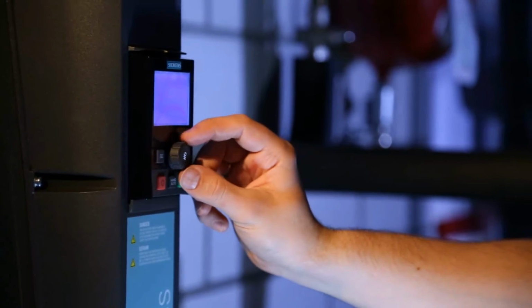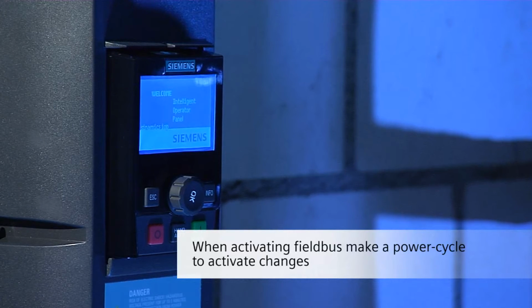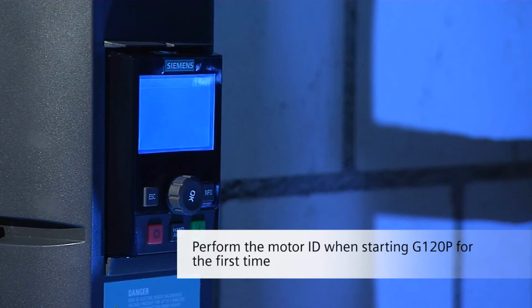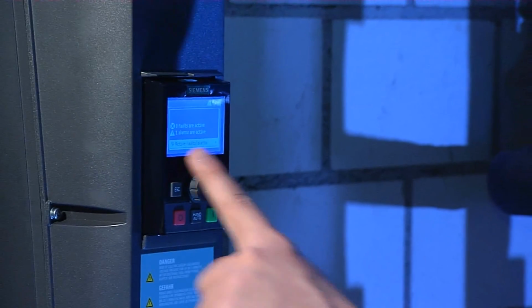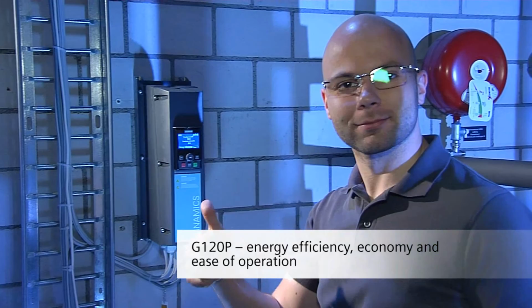Your drive is now almost ready for operation via Modbus. Toggle the power once in order to reboot the control unit so that all Fieldbus settings become active. The Getting Started guide gives more information about other Modbus parameters, such as baud rate and timing. It's this easy to commission your G120P using IOP.